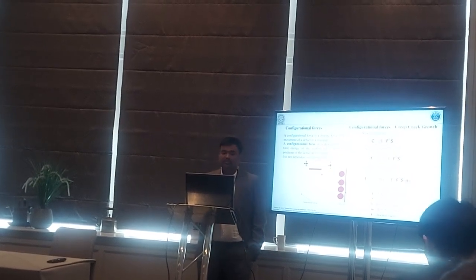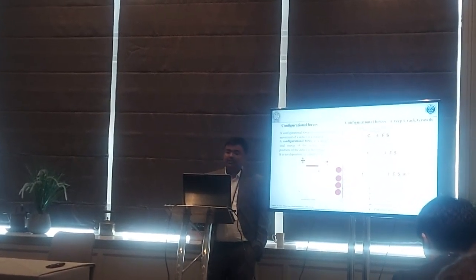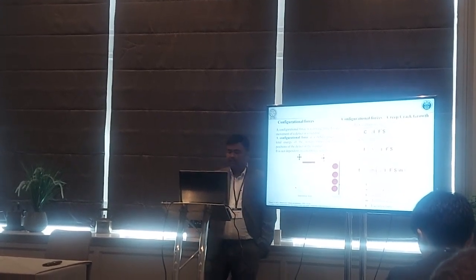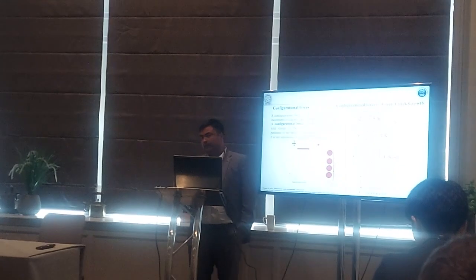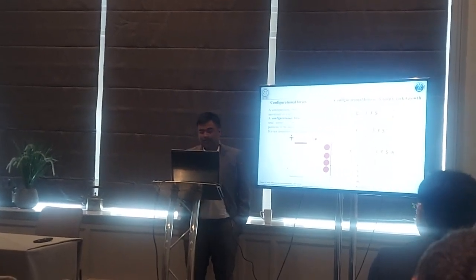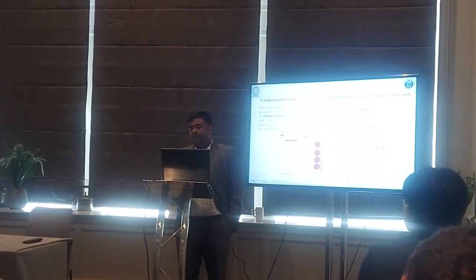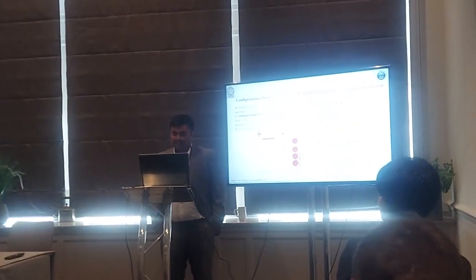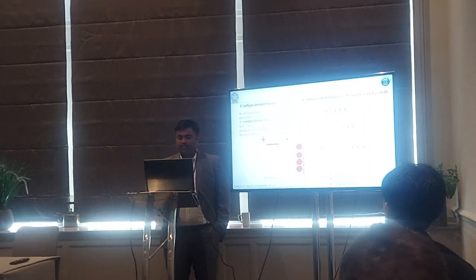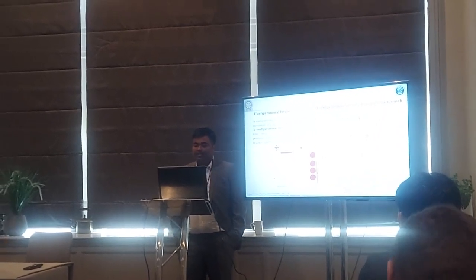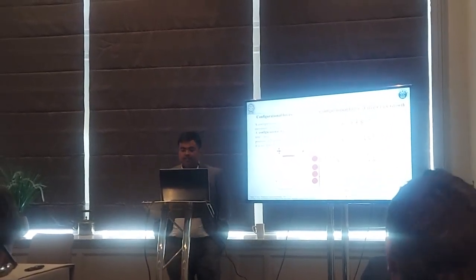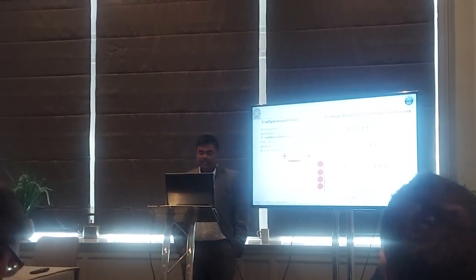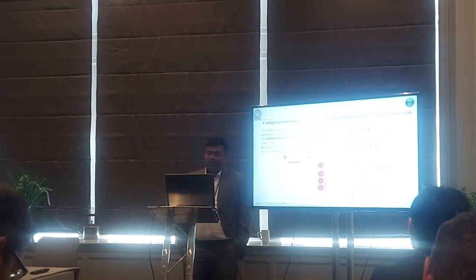So by using this concept in the field of fracture mechanics, the bulk configurational forces, with the help of this expression, I have to apply to find the configurational forces where the material is creeping. So C is a stress tensor, whereas phi is the energy density, I is the identity tensor, F is the deformation gradient, and S is the first Piola-Kirchhoff stress tensor.